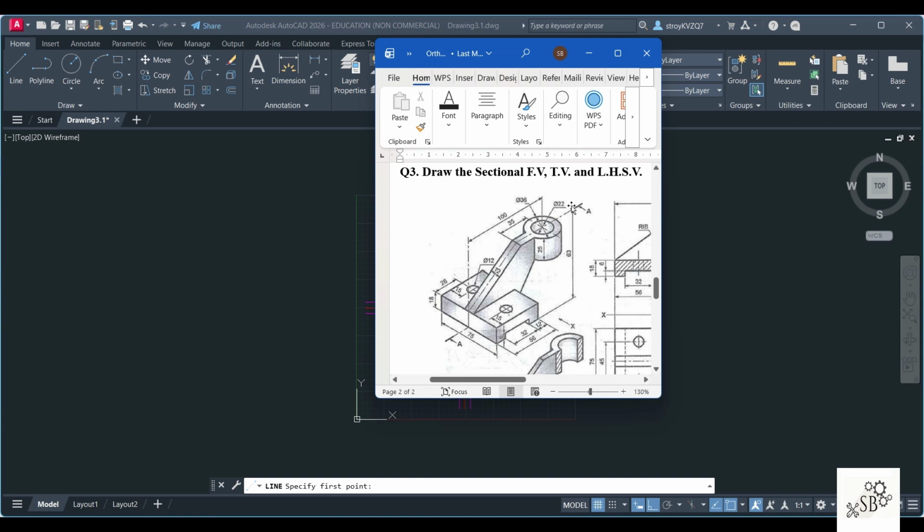This is the height of this total front view. So from the bottom, if I draw this center line, as you can see over here at 63, I should be able to start. And then if you observe clearly, at a distance of 18, because the outer circle has a diameter of 36, so this half is 18. Here you will have to draw another center line, and then this will look like a rectangle from the front view, because you have a circle outside and a circle inside. The outer circle has diameter 36, the inner circle has a diameter of 22.